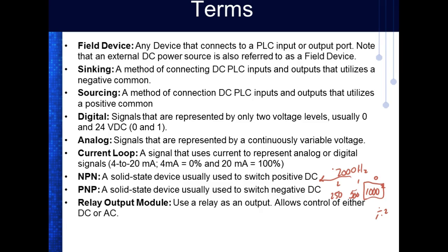The problem is we do that all the time. We make light flashers all the time. So what did Allen Bradley give you? They gave you a register that just sits there and counts. All you have to do is pick how fast you want it to count, in multiples of 2, and use that to flash your lights. If you want to do it three times, you bring it into a counter. Every time the counter is enabled, you turn on your light. Every time the counter is disabled, you turn it off. After three counts, you reset it and you're ready for the next one.